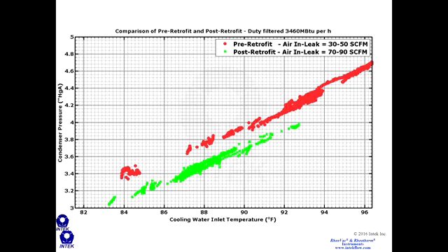And something to note here is that their air in-leakage actually increased during this outage. It was an unfortunate thing that occurred, but their air in-leakage actually almost doubled over the course of performing the retrofit. But despite that higher air in-leakage, we got 0.2 of an inch pressure decrease, and if this air in-leakage gets reduced, this back pressure should go down by another 1/10 or 2.